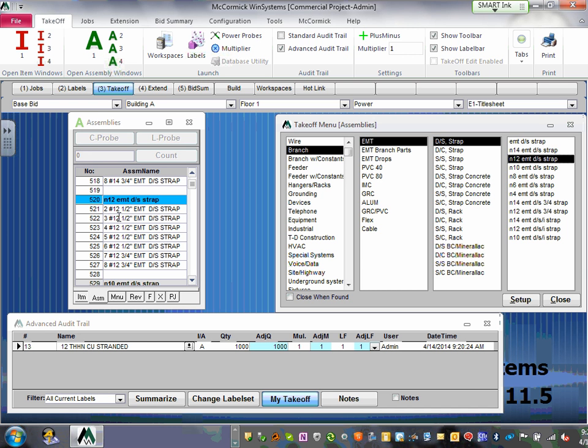I have 1/2 inch. Can you guys see what it defaults me to, Adam, a bunch of things? I can have 3 conductors, number 12 in 1/2 inch, or 2 conductors, or 4, 5, 6, 7, or 8 conductors, gentlemen. Can you guys see the options that you have? And if you look underneath it, here's number 10. Number 10 conductors are right underneath it. So what does that mean?